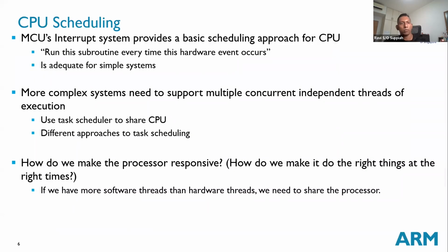Okay, so in terms of the scheduling of the CPU, of course, we don't necessarily have any particular scheduling because we just go ahead to write everything in the main loop, plus we have interrupts. All right, so of course, what we want is to make the processor more responsive. The responsiveness comes naturally when we have the hardware-driven interrupts, because the moment the interrupts come in, the processor is able to respond.